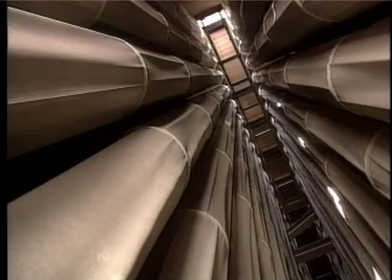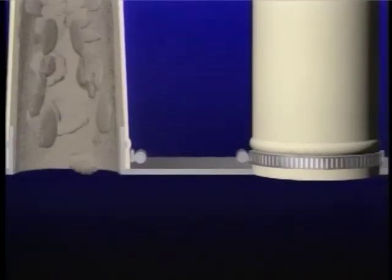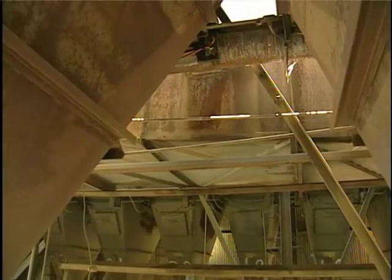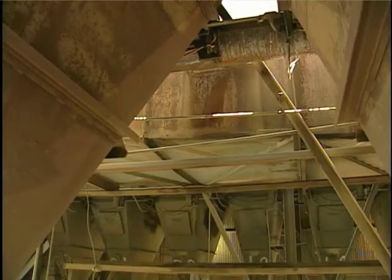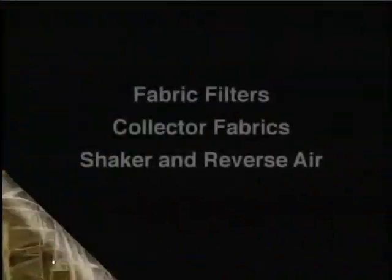To keep the bags from fully collapsing during the reverse airflow, rigid rings are sewn into the bags at intervals along their length. The dust cake dislodged by the reverse airflow falls into the hopper and is removed from the collector. The gas that was used for cleaning flows out of the hopper and into the hoppers of the operating compartments.